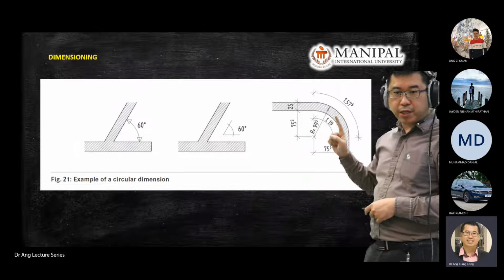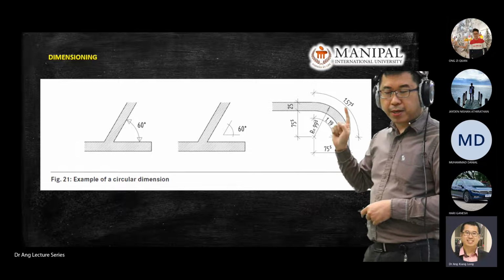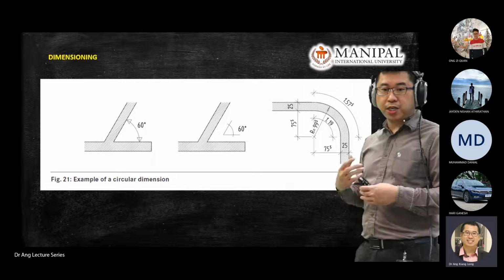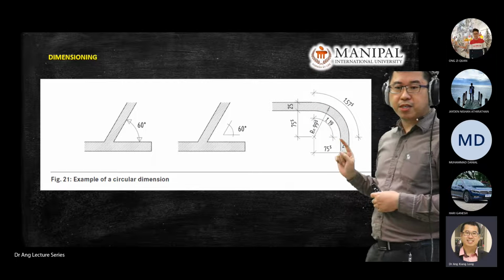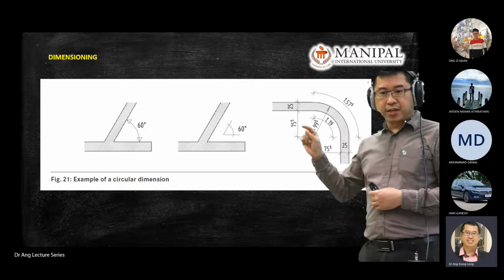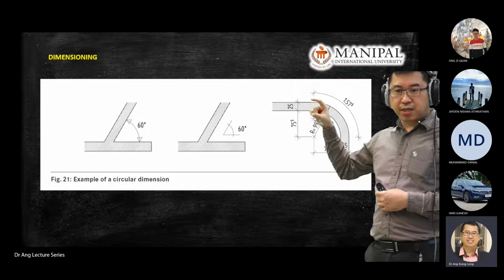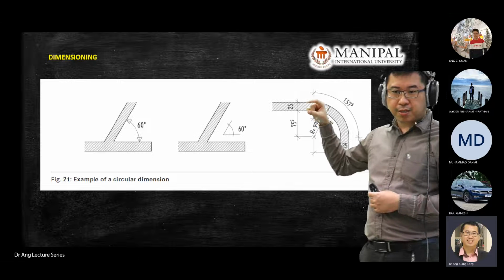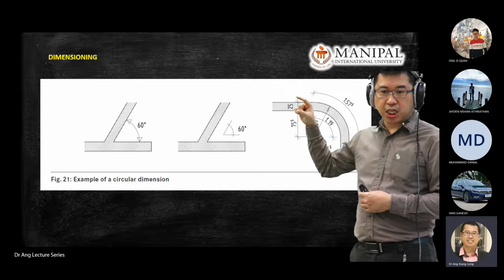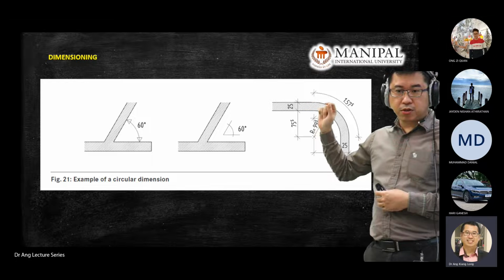The first drawing you submit to me, you're using this one, but after some consideration, after you've done simulation, you found out that this corner experienced high stress, and you need to make this component a bit thicker. From 25, it increased to 30. So there's a new revision of the drawing.